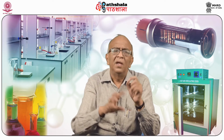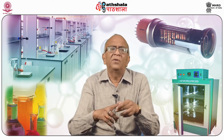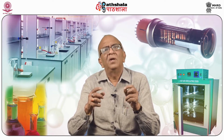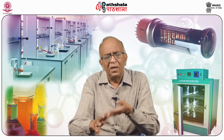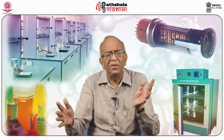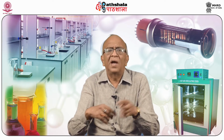First, to collect a sample, and the sample should be a homogeneous sample which has all the characteristics of the compound. For example, if I want to collect an air sample, it should have composition from different places, and then we mix it. Or if I take a sample from water, it should be from different places of the river or water body, at different sites, at different depths. So we may have a representative sample. That is called sampling.